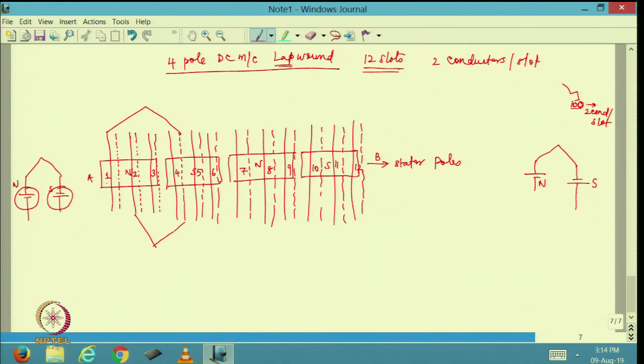So you can understand that from 1 it has gone into 4 backward conductor, from 4 it has come back to 3. So backward pitch is 2 slots behind, that is 4 minus 2 is 2. So this is essentially 2 slots behind, whereas this is 3 slots forward.